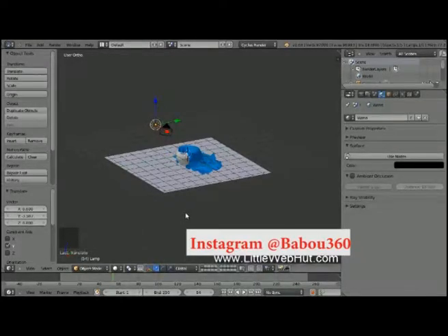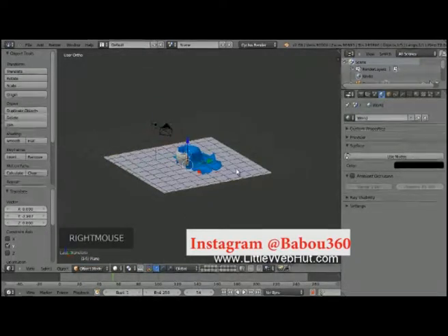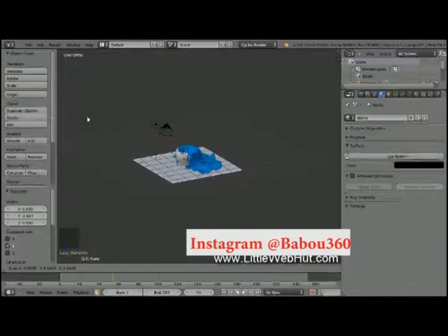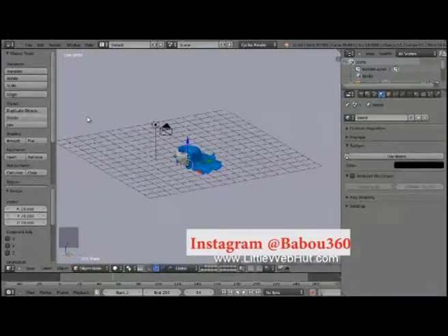Now I'd like this surface that the cup is sitting on to fade to black in the background. To achieve this, we just need to make the surface very big. So right-click on it to select it, then click on the Scale button, and type 20 followed by the Enter key. Now let's set up the camera view.